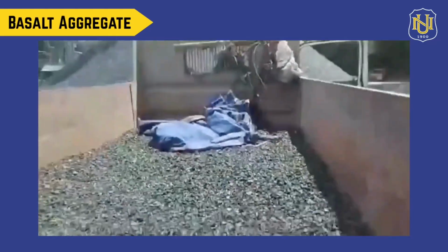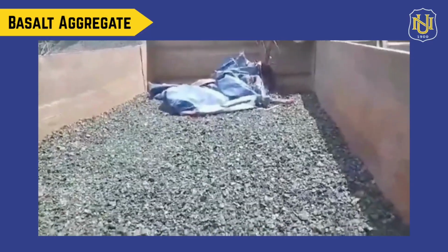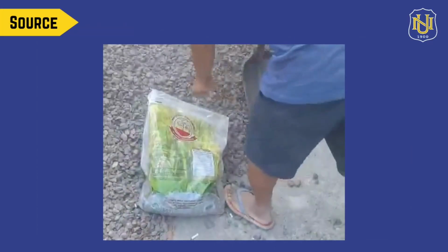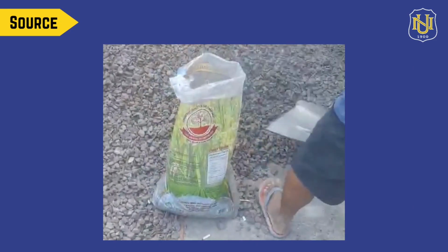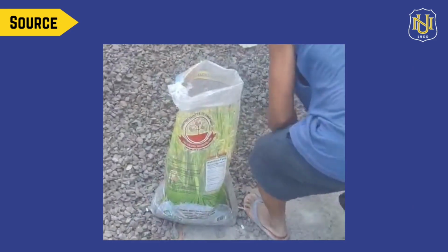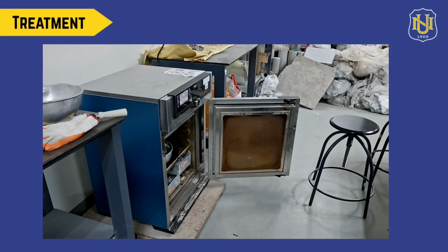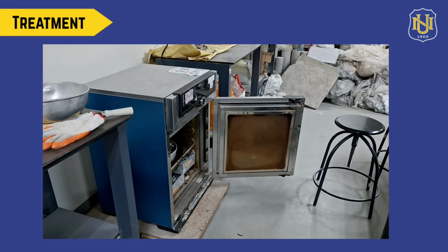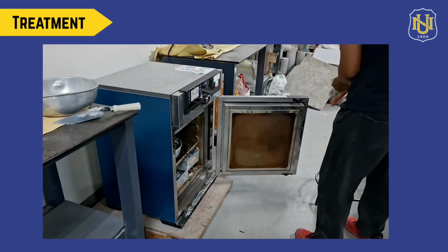Basalt aggregate was used in this study as an alternative coarse aggregate material. Basalt is a dense, volcanic, igneous rock known for its durability and strength. The basalt aggregates used were obtained from a local source and prepared with sizes ranging from 10 to 20 millimeters. To maintain consistent moisture content before mixing, the basalt aggregates were oven-dried at 200 degrees Celsius for 30 minutes and allowed to cool overnight.